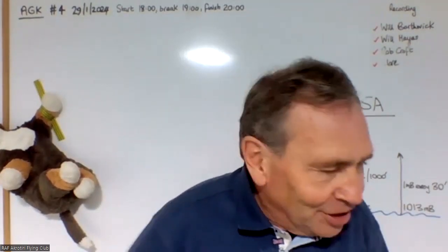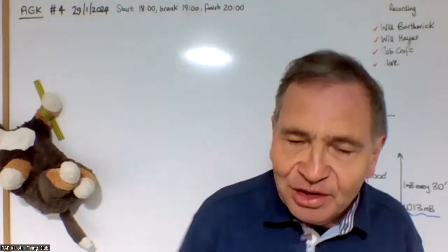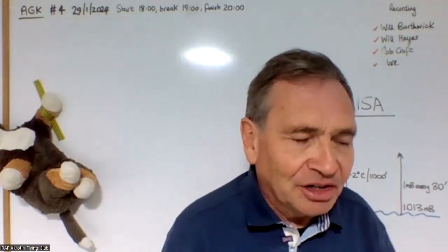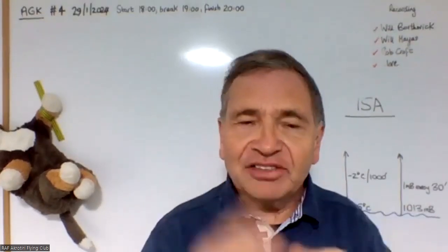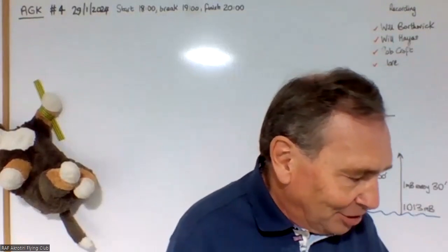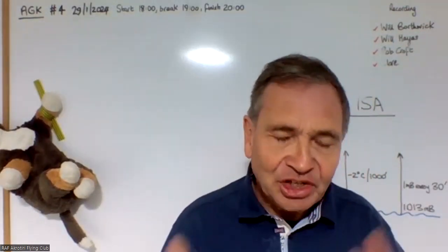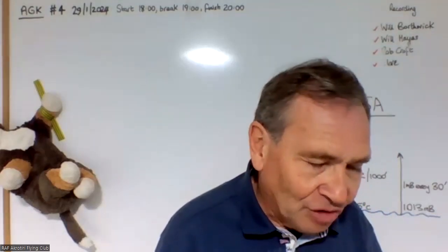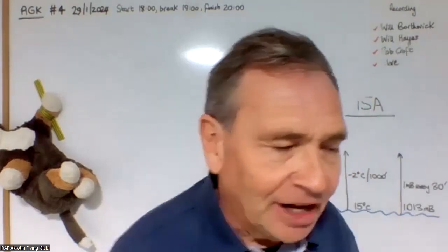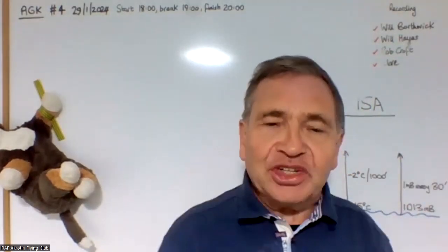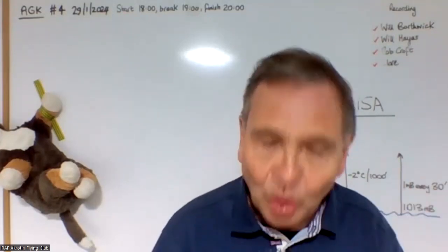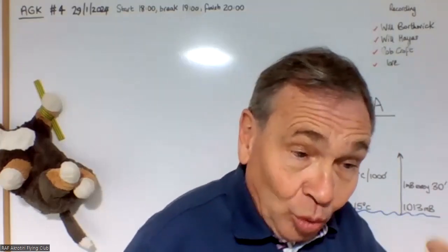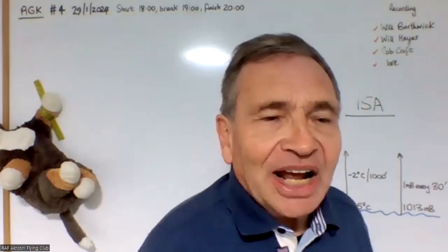But you are absolutely correct, Rob, because as soon as you lower the air pressure, moisture comes out of the air, because we alter the relative humidity by lowering the pressure. If moisture comes out, the air has to cool, which can make the water that's condensing actually freeze.